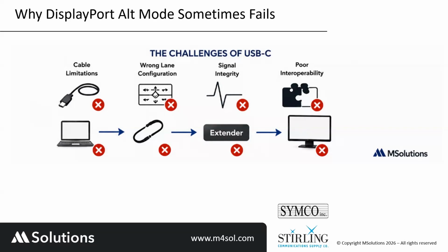That's true, but it is true if you're cycling plug in and out of a USB connector. In many cases, when it doesn't work the first time, it doesn't mean that the cable or the connector is not good. It's more about the capabilities of the device that the cable is connected to provide all the capabilities that are required by the system. So those are the things that you need to remember when implementing a USB-C system.